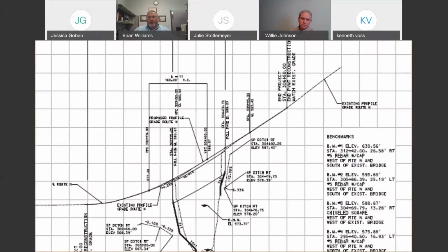So looking at other BMPs or potential permanent BMPs we might want to look at in those areas if erosion is truly a concern. So you've got 6% grades on the other side, 2% to a 6% grade going off into the right ditch. So we know we've got some substantial grades there, so we know we're going to need quite a few BMPs.